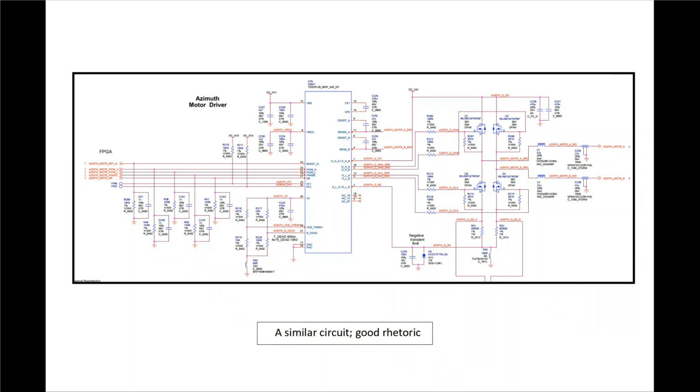Now the whole page begins with the schematic symbol for the IC, and that was created with the page layout already in mind. The logic inputs are on the left, the FET gate drivers are on the right. Power is at the top, ground, and the configurations that need that ground, they're at the bottom.